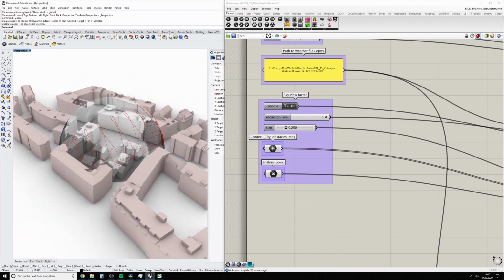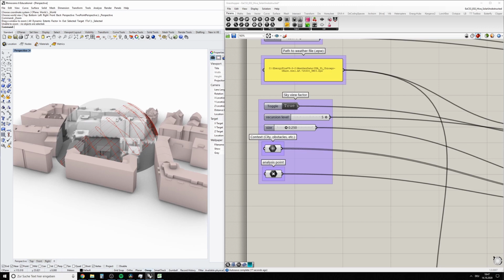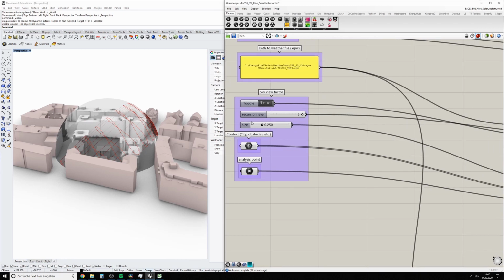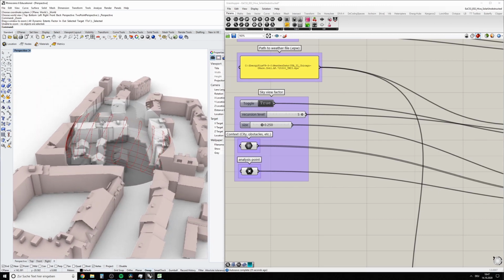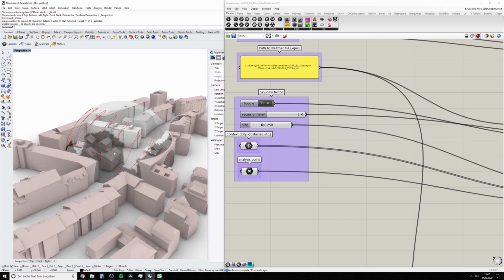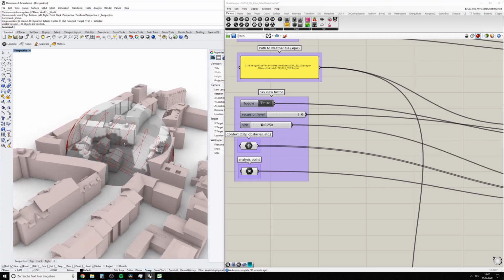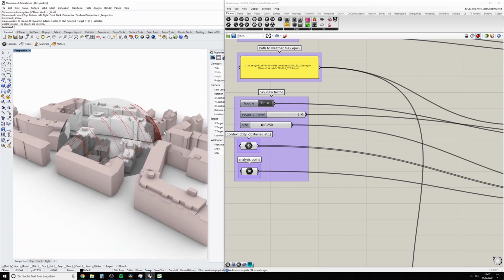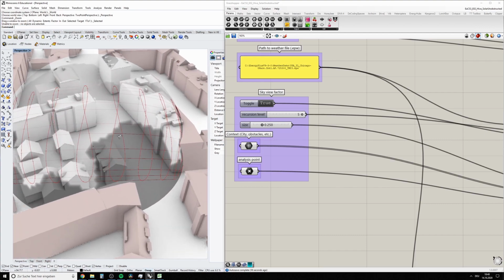And in this context, it's always nice to keep the sunpath also activated, which actually is always on by default in this example. But I'll show you in a second how to deactivate it. Because now, if you have the sunpath overlaid to the sky view factor sky dome, you can very quickly see which parts of the sunpath are covered.